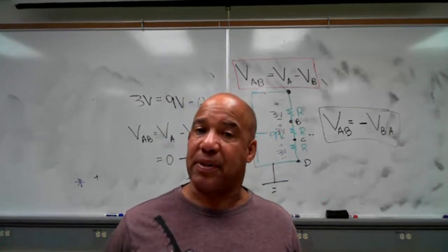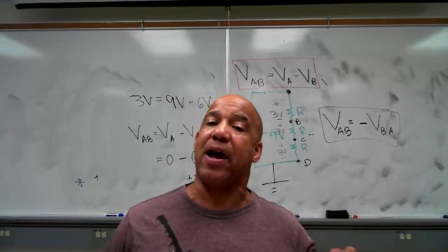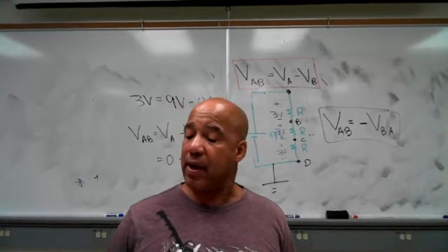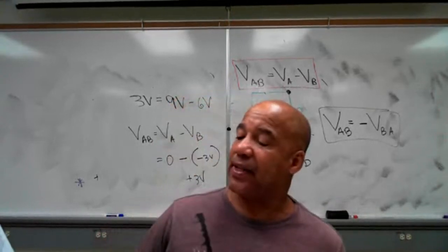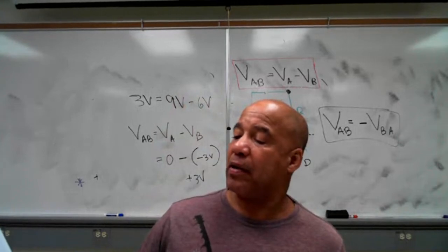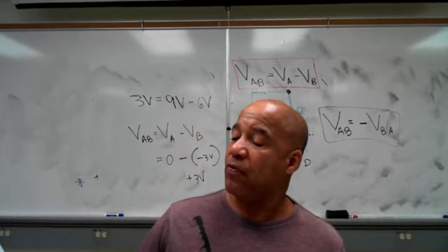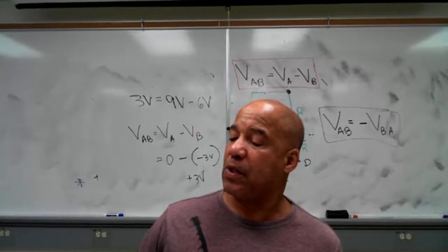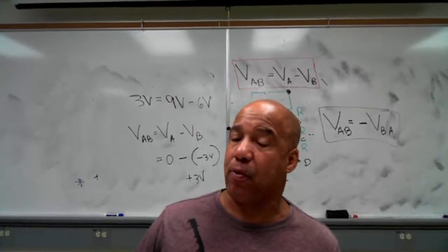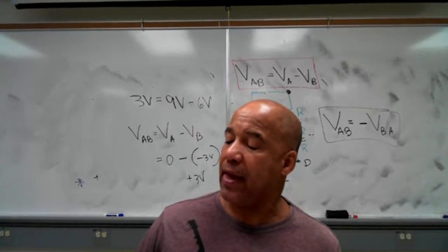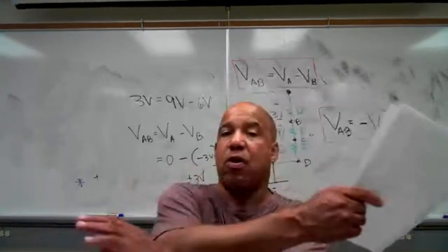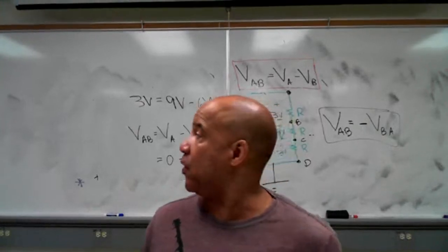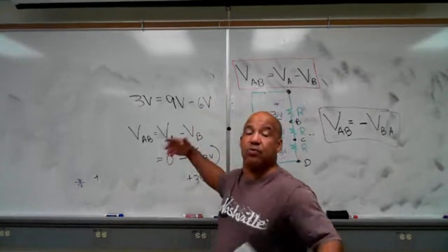Since those are single subscripts, those voltages are taken with respect to ground. And you've got to look at the circuit to see where the ground symbol is. In this case, it's at point B. So the measurements he got, and it makes sense: the voltage at A with respect to ground is what? 4 volts. The voltage at B with respect to ground is 0 volts. And now if he goes to the voltage at C with respect to ground, at that point, your black lead is at point B in figure 4.1A, and your red lead is at point C. Then you've crossed them, so you're going to read a negative voltage. So they have a -8. But the total voltage, if you were to use this equation across each resistor, would stay the same.